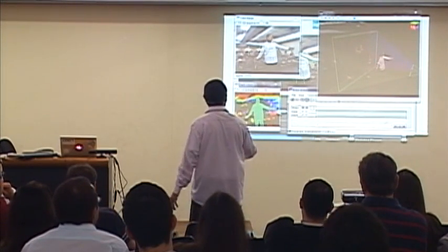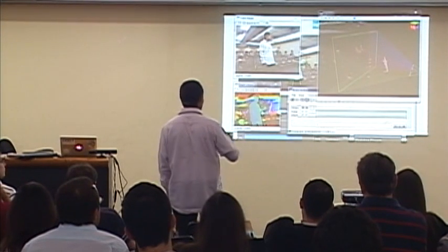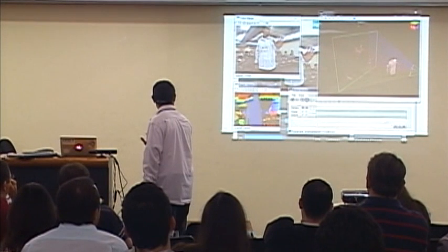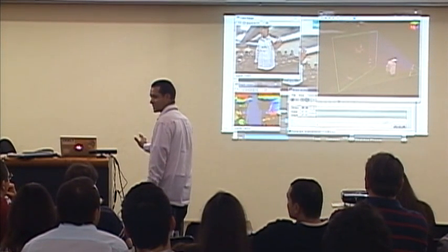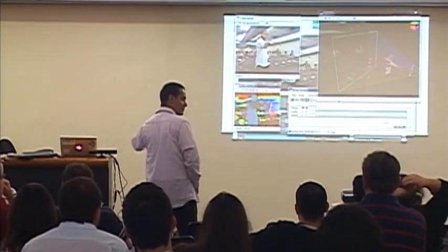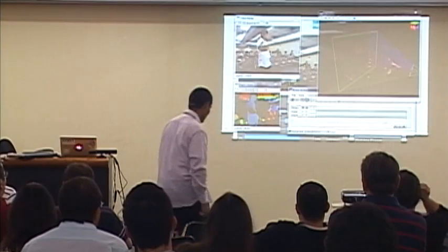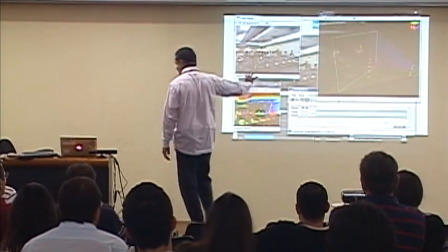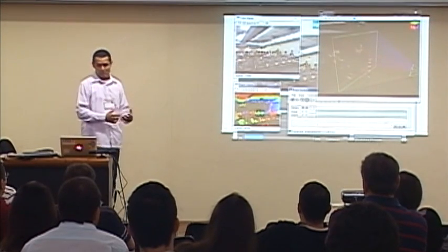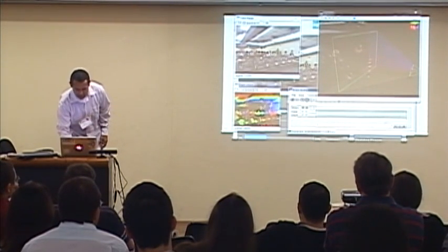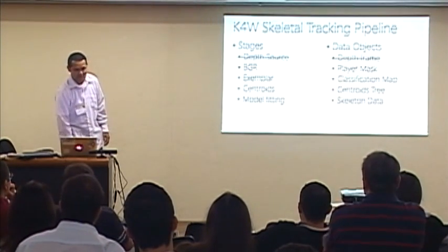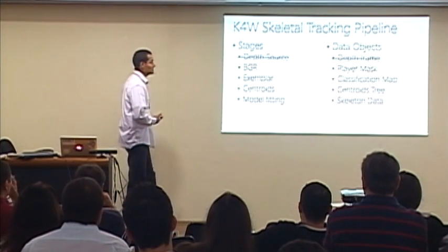And you can see some lines, for example, the device, when it is in the Xbox mode, which is the default mode, it cuts depth when I come closer to 80 centimeters. Okay? And I can put it in what we call mirror mode, and it will give you the depth even when I'm 40 centimeters away. So, did you all get the idea of that view? Basically, I can then have this depth map being used as the basis for my segmentation, isn't it?